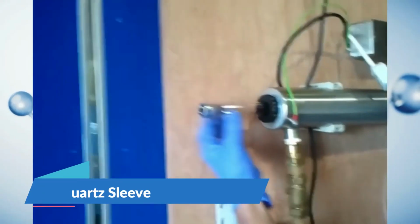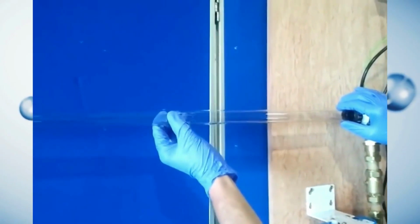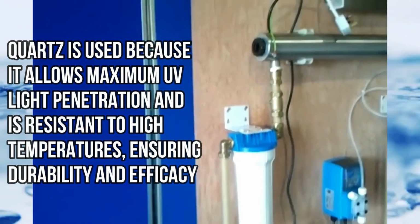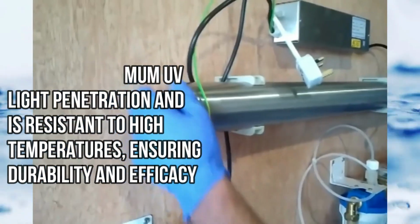2. Quartz sleeve. Function. The quartz sleeve houses the UV lamp and serves as a protective barrier that also ensures optimal UV light transmission. Properties. Quartz is used because it allows maximum UV light penetration and is resistant to high temperatures, ensuring durability and efficacy.